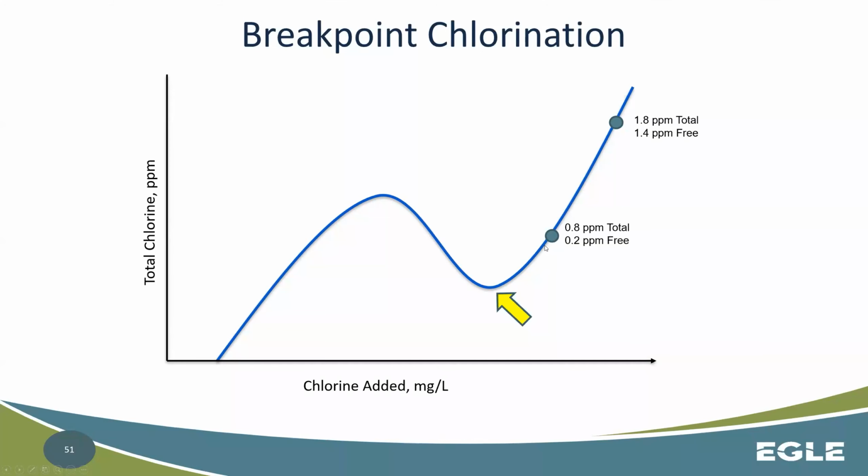And then when you start coming out the backside, this is when you're going to get odorless chlorination in your system. You've burned through all of those things that create that chlorine odor in the water, and you're actually starting to get water that's free of those spent up combined chlorine issues. You're starting to get to the free chlorine piece, and that free chlorine then starts to build in residual concentration.